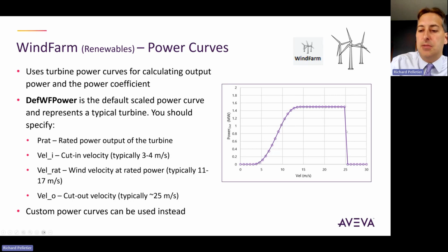And then you'll see this dip here because most of the time these wind farms, when there's a certain velocity point where it's higher than that point, it becomes unsafe for the wind farm to operate. And so they'll shut down the wind farm so that it's not blowing at such a high speed, to protect it from any damage that may cause. And of course, when it's shut down, there goes your power, right? So you'll see this dip a lot of times.